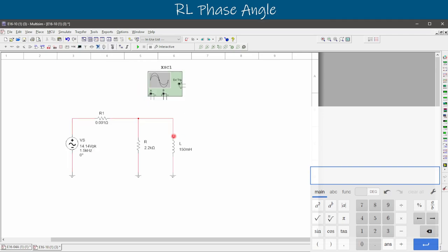And here is our 2-channel oscilloscope, and we are going to measure around our source voltage on channel A. So positive lead goes to the top side of our source. That's anywhere above the source, but before this first resistor we just placed. And the second one, the negative lead, is going to go to ground, any ground technically, but we'll put it on the bottom side of our source over here to keep it consistent.